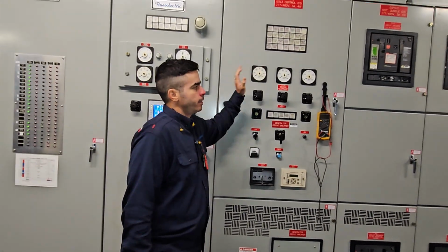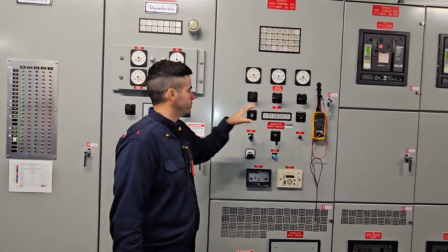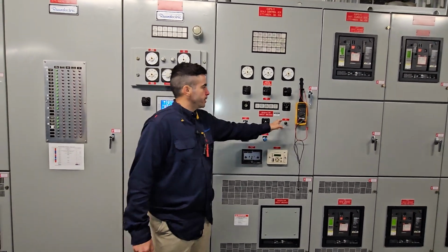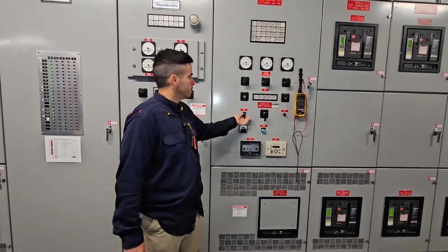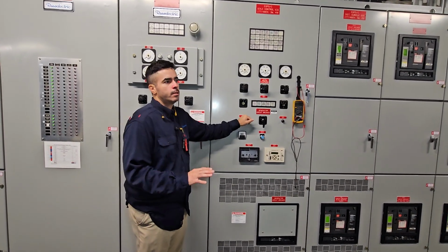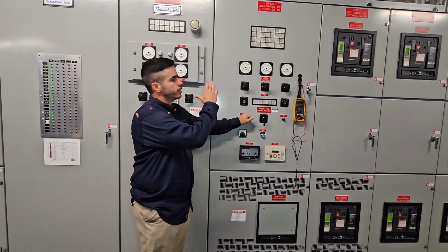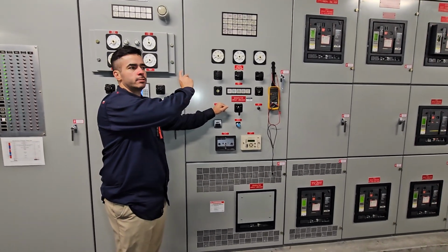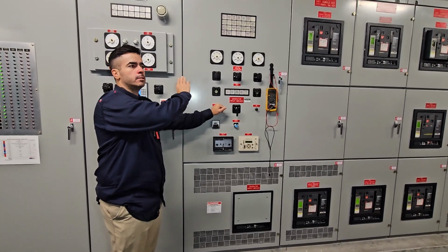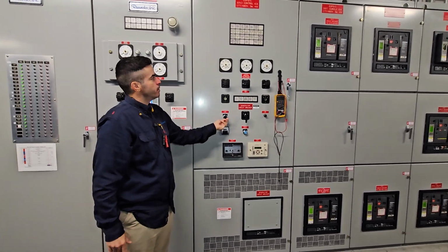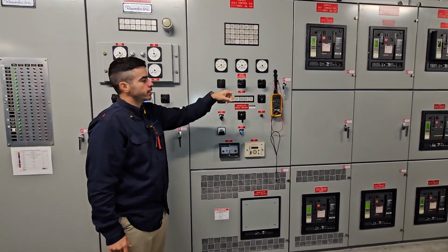So we already talked about the generator features that we have here. Then we have the voltage adjustment and the speed adjustment here. This is something that you usually don't have to deal with unless there is a very weird condition, again, like the generator pushing amps when it doesn't have any load. So you might want to adjust the voltage a little bit. We're going to do that in a second.